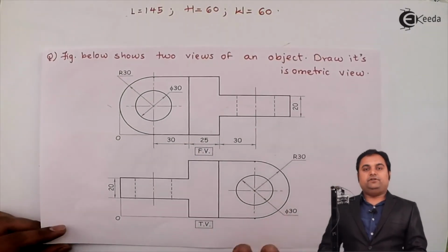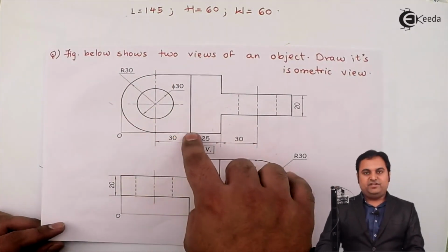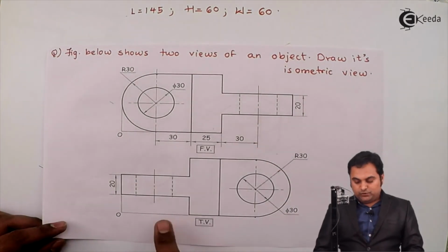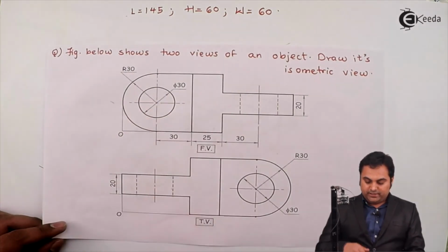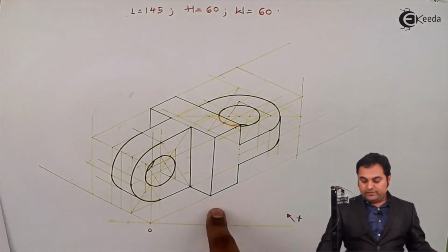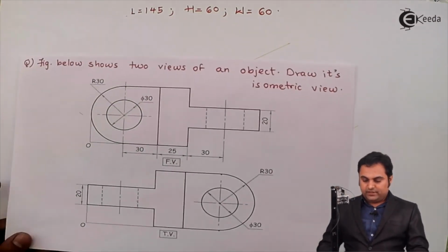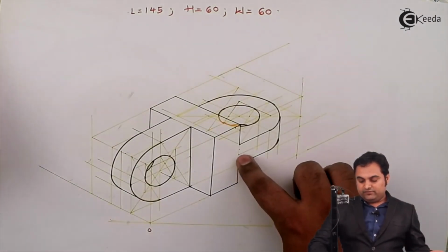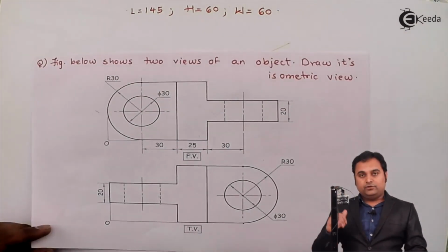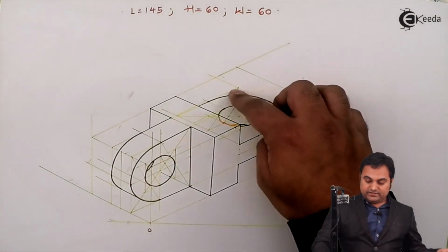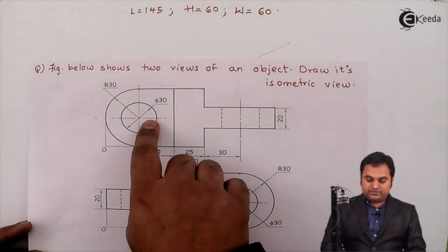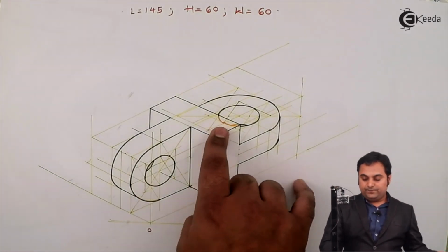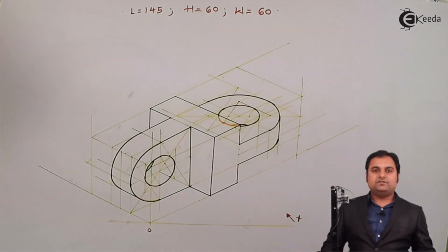Now, when I look at the front view for this question, here the semicircle is seen and then there is a dark line. It means both these surfaces are on different planes. So when looking from top, it is understood that this semicircular portion is behind and this surface is ahead. So that can be seen from the front view. Next, this semicircular disc appears as a straight height of 20 mm, which is there from the front view, looking like a rectangle. From the top, this portion is seen as a semicircle. It is seen as a semicircular portion, and this portion, semicircular disc, seen as a rectangle. So once I have drawn this and there are no intersections here, only up to the dark portion, and with this we complete the problem.